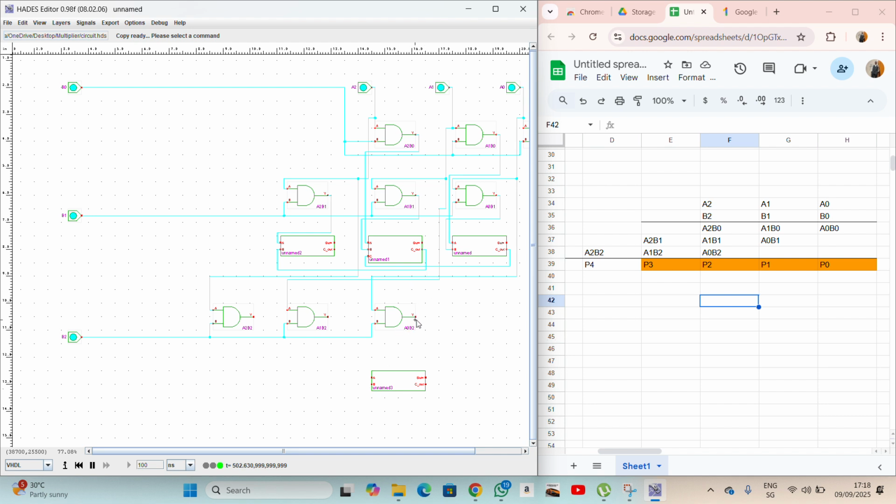So we are going to add this sum here, this sum, and it's going to be added to this variable that we have on this part here. So it's only two things that are being added, but the sum is going to be here, where the C out is going to come out from this point. Now the C out must be added to something. Now if you look at this column, we have the sum here, and this sum should be added to this plus the C out that comes from this one. That's why we need a full adder here.